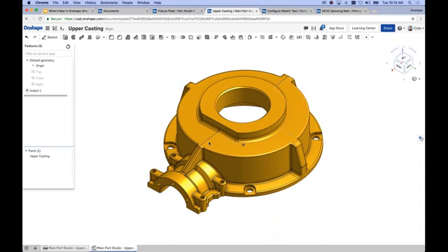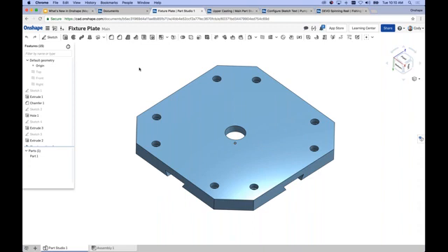And this is the real limitation in the past. If I created an assembly and inserted these things together, I couldn't edit one in the context of the other because they were linked, right? So how would you do this? The important first step, and this is not new, it's just worth mentioning again if you're using a lot of linked documents: you have to create a version before you can insert as linked.